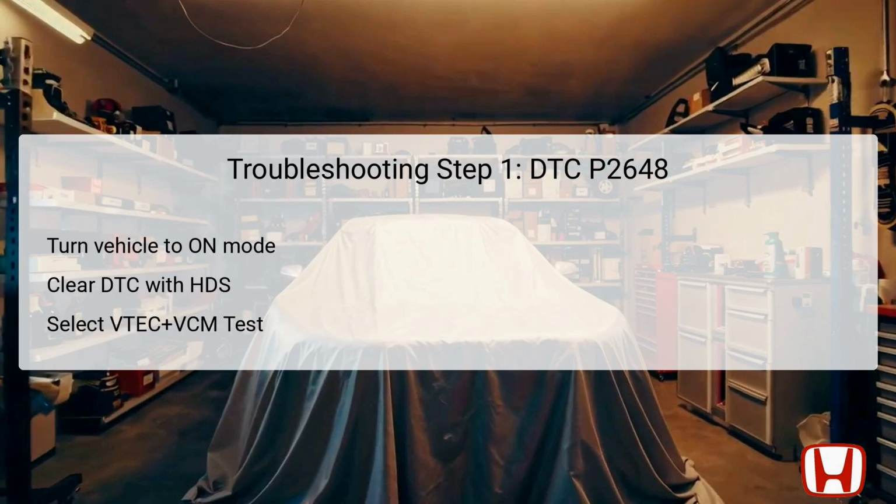In the first troubleshooting step for DTC P2648, it's essential to start by turning the vehicle to the on mode, which allows systems to initialize and be ready for diagnostics. After this, the next action involves clearing the DTC using the Honda Diagnostic System, HDS. Clearing the code resets the system and allows for a fresh check to see if the issue reappears.